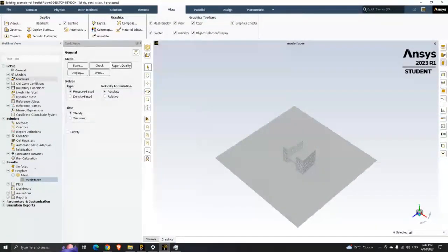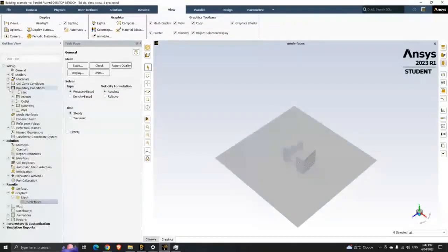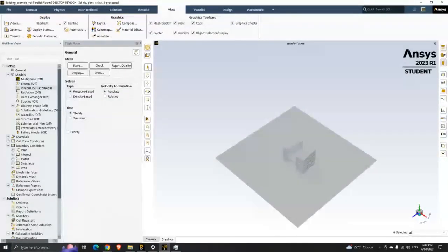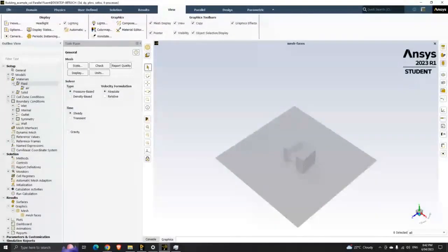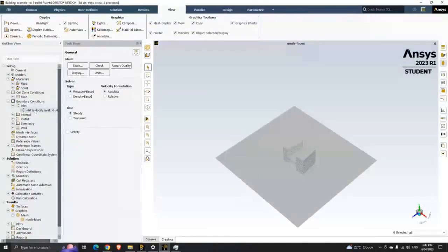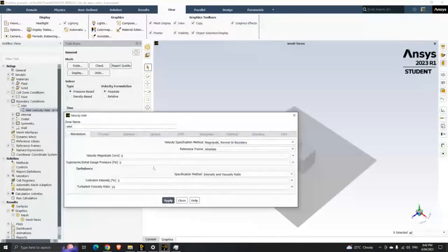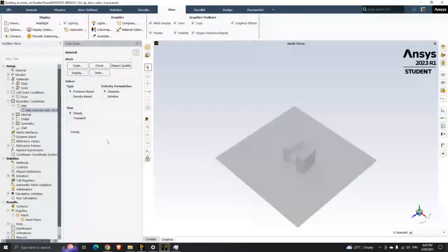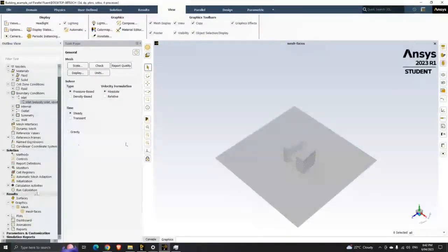And then what I'll do is I'll quickly set up the simulation. For now, I have the SST omega model as the turbulence model, because I'm not considering any other physics. This is enough. And air, I have the materials where air is a constant density gas. That is fine. We will use inlet flow velocity of about 10 meters per second. It doesn't look like a lot, 10 meters per second, but trust me, if you are in a 10 meters per second flow, you'll have difficulty in standing up.